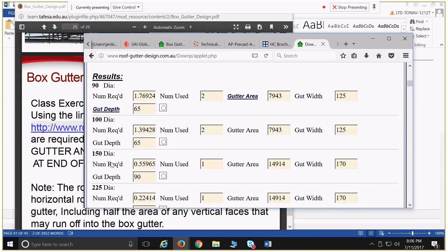Would that affect or cause issues with the sloping, which will affect the aesthetic looks of the building? Yeah. If you want to consider the building aesthetically, running just one downpipe for the whole building. To make it look like you're running the gutter all the way around the building and you just go to one. Yeah. Well then, yes, if they consider things like that. In the case of this, I said 90 diameter, and just 2 downpipes.